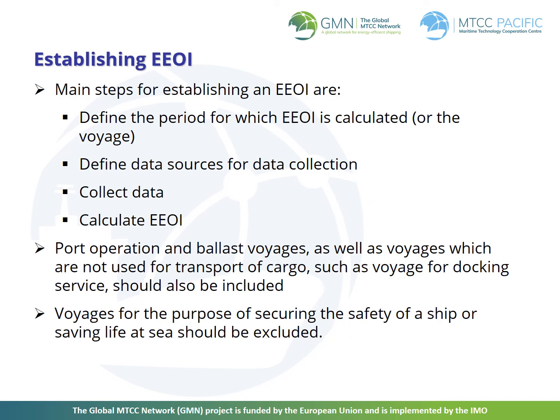The EEOI should be a representative value of the energy efficiency of the ship operation over a consistent period, which represents the overall trading pattern of the vessel. In order to establish the EEOI, the following steps will generally be needed. Define the period for which EEOI is calculated, or the voyage. Define data sources for data collection. Collect data.